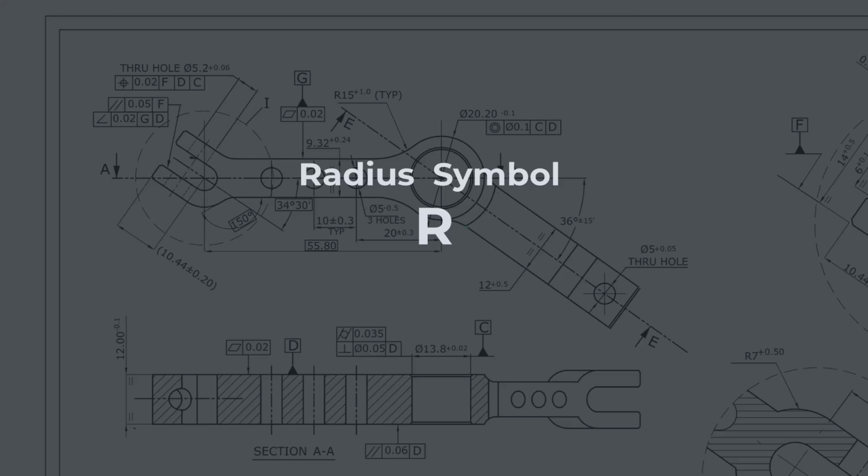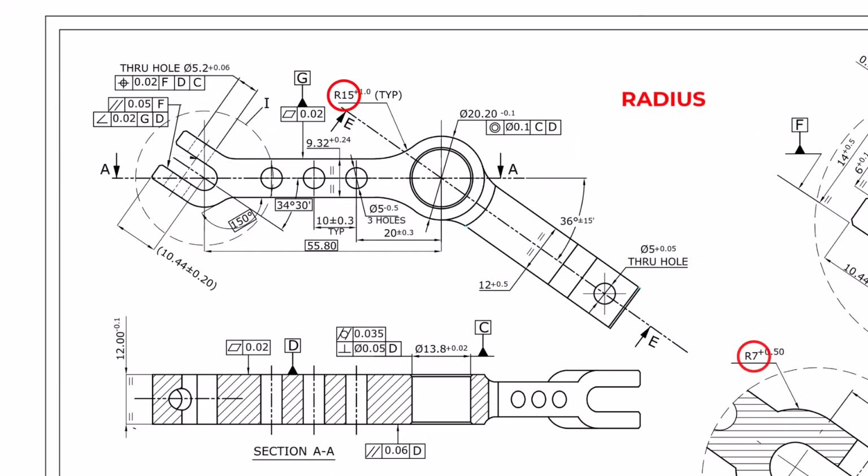Unlike diameter, which describes the entire circle, the radius measures the distance from the center of the circle to its edge. Radius dimensions are commonly used for rounded corners, fillets, or curved transitions, mostly arc-like features. Why are these rounded corners important? Because sharp corners create stress concentration. Round corners help distribute stresses more smoothly and improve the durability of the component.